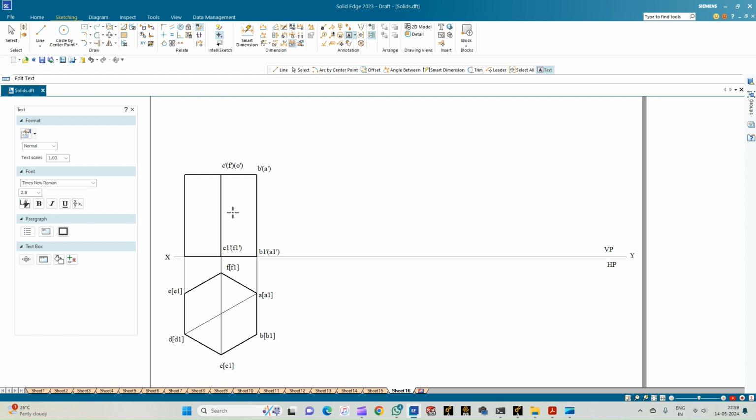So the axis is not visible here. Similarly, here inside the bracket it is O1 dash, and coming to this edge, it is D1 dash, which is visible first, and inside the bracket it is E1 dash, and here this is D dash, and inside the bracket it is E dash.